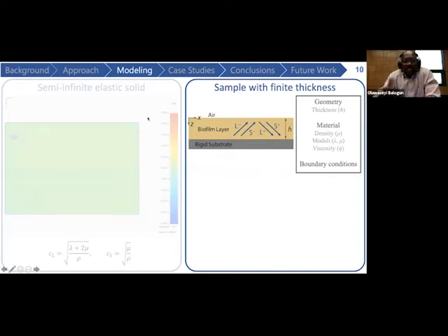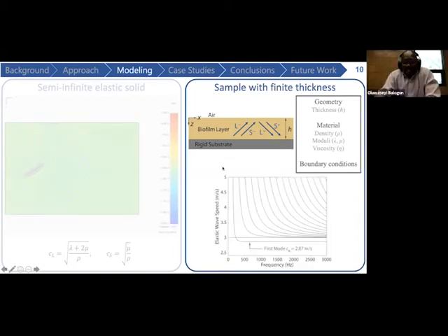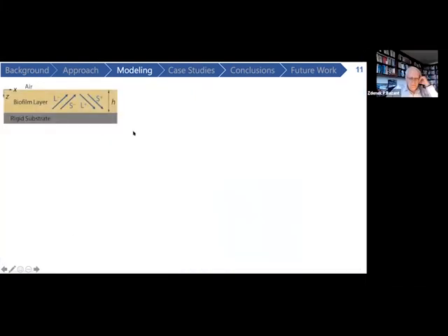And so naturally, it lends itself to some sort of numerical analysis, and I'll explain exactly how that's done. We're going to set up an elastodynamic wave model, and then use that to predict the wave speeds in these materials as a function of frequency. Going back to the problem statement, we have a biofilm on a rigid substrate. The substrate is essentially free of any deformations because it's much stiffer than the soft, gel-like biofilm. And then we account for the boundary conditions of the surrounding media.